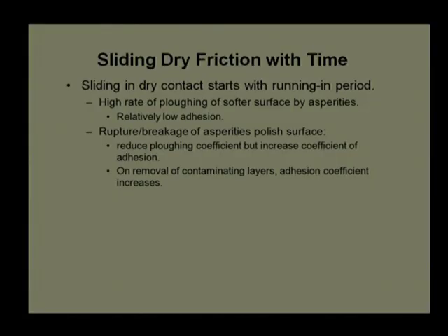However, there is a possibility of change in coefficient of friction even under steady running conditions. When we bring two new, fresh surfaces together, there will be a higher plowing effect at the start and relatively low adhesion.